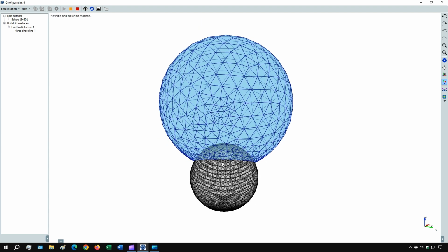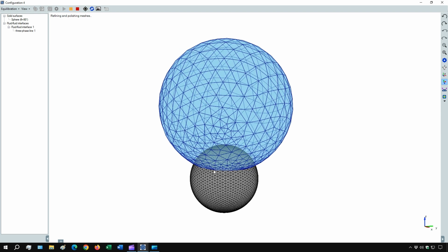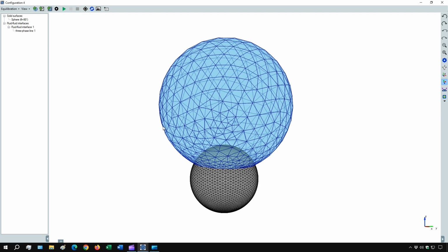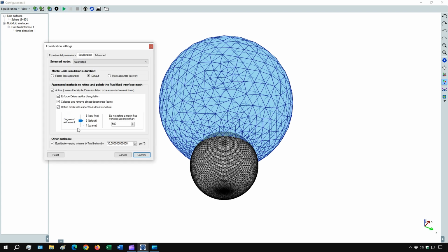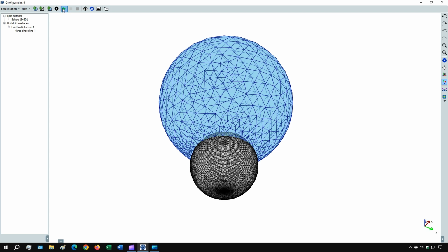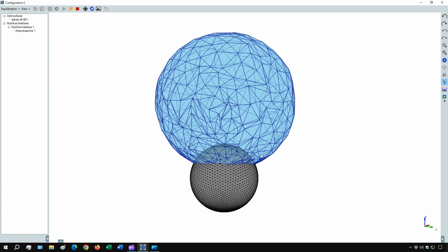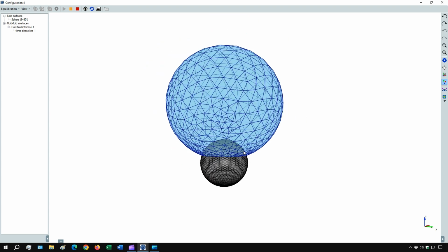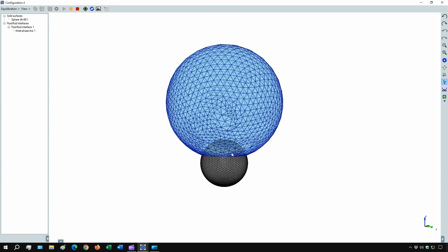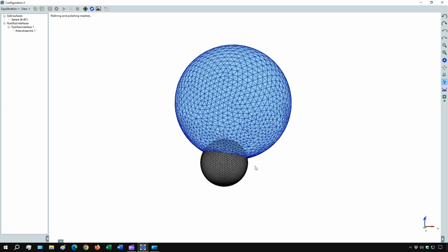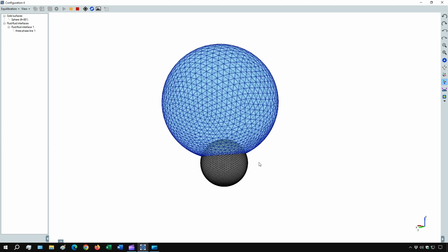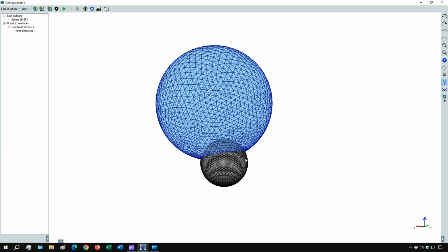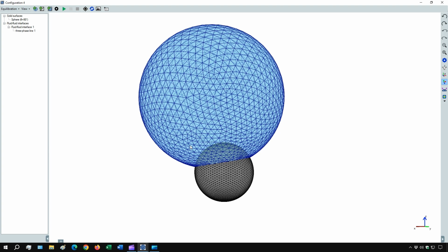As long as the option to vary the fluid volume is selected, the volume variation will be enforced whenever launching a new equilibration. So, if I now launch a new equilibration, the current droplet will be enlarged by another 30 cubic microns. If you want to assign a precise total volume to a droplet wetting a curved substrate, then this option to modify the fluid volume becomes quite useful.